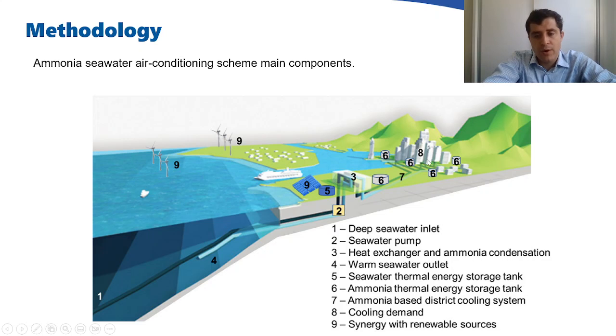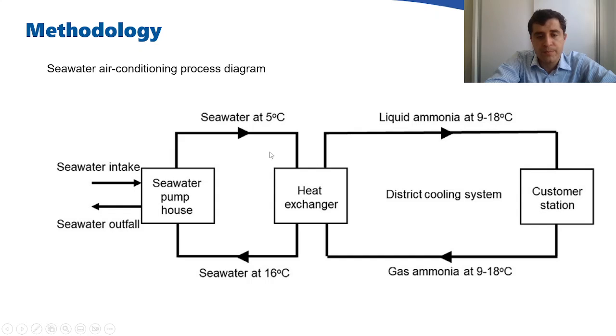The ammonia vaporizes, and then it's automatically directed to the condenser because the pressure is lower, so you don't need compressors, for example. It just flows to the condenser because the pressure in the condenser reduces as you condense the ammonia.